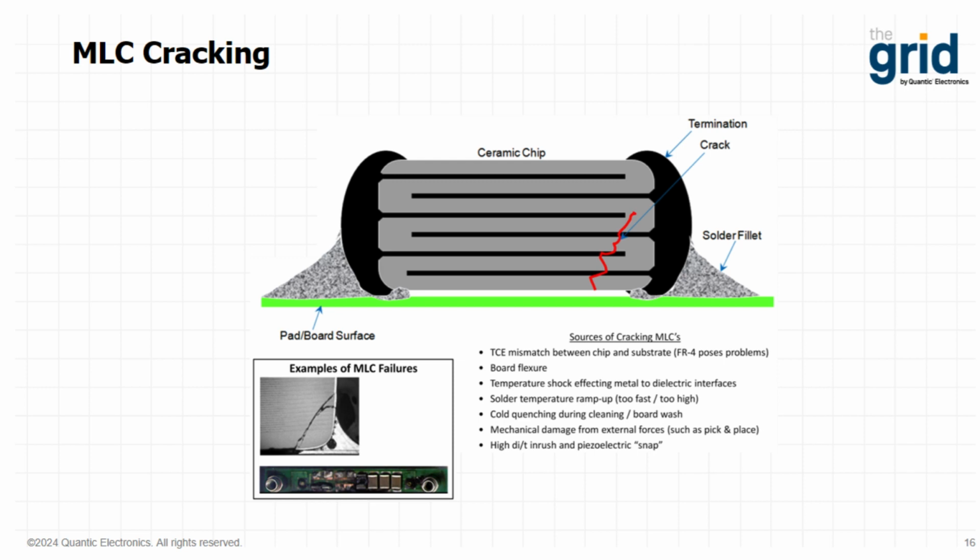This could be from various conditions, including thermal shock, handling during manufacturing, handling during use, board flex, also electrical piezo effects that could be caused by strong electrical pulses, specific waveforms that the capacitor is seeing, things like that. Here on the bottom left of this slide, you will see some cracked ceramic capacitor cross sections. You can see the solder fillet here with a well-defined crack.